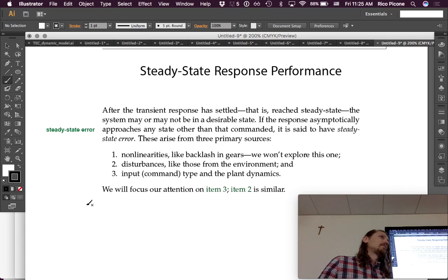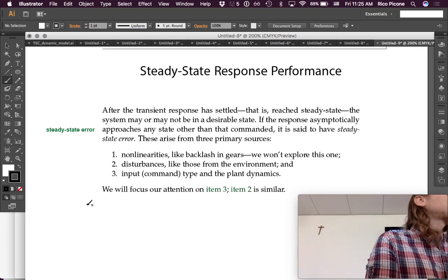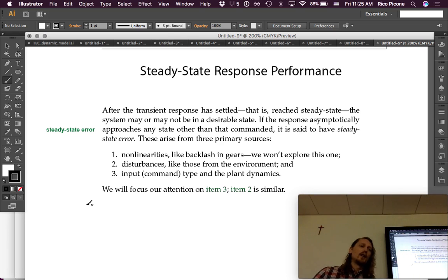Do you input it in such a way that basically the backlash is accounted for? Like the first however many revolutions is 0? Well, yeah, the major issue with that is that it's hard to predict what it's going to be when you set things up. You can predict it okay sometimes, depending on the situation. It changes over time too, so as the gears wear, it changes. And for every specific machine, it would be different. You have to calibrate it. It's not ideal,